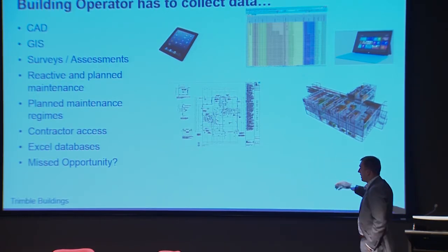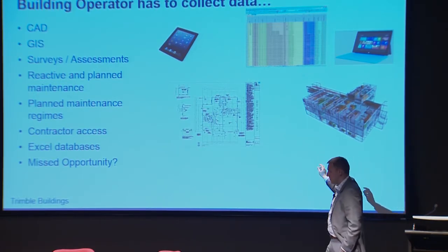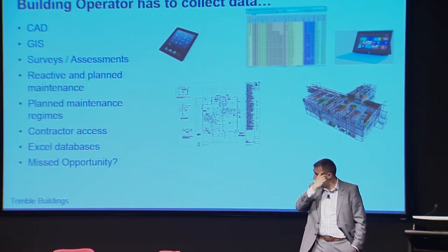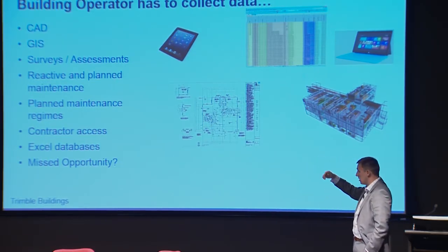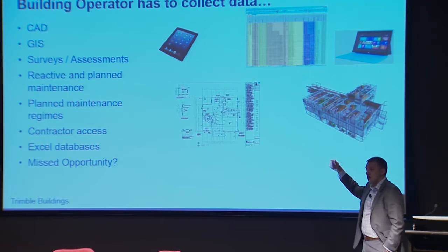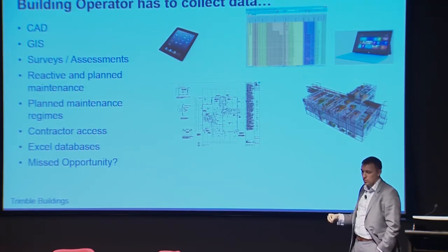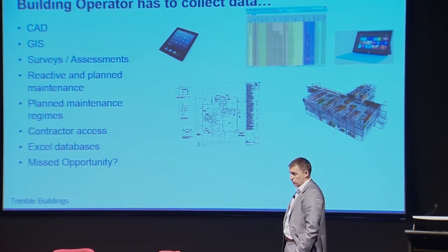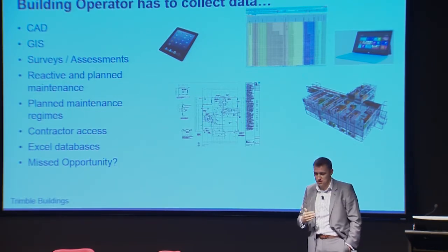But if you don't do that, then you get into the operational phase. You have a building you don't know enough information about. That leads you to potential problems downstream with the maintenance programs. And you might have to go out and either resurvey through CAD or use some GIS information, or actually walk around with tablet devices undertaking condition and defect surveys, or even just a full asset capture exercise.